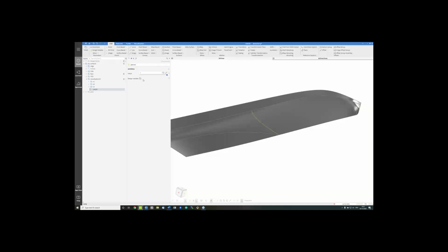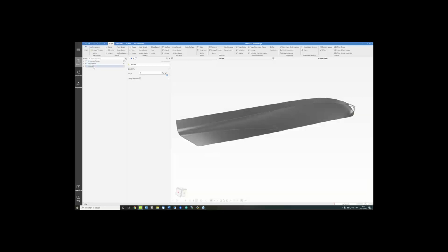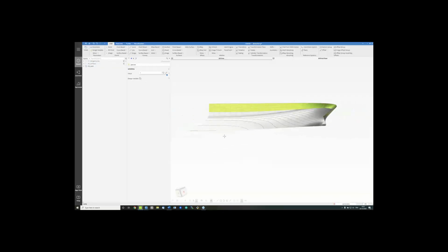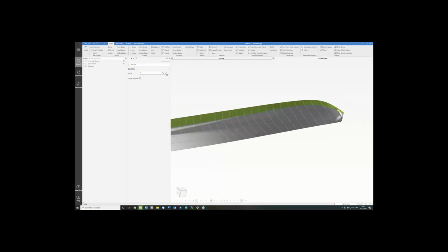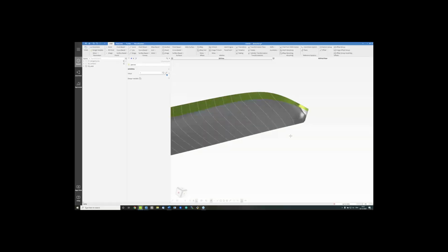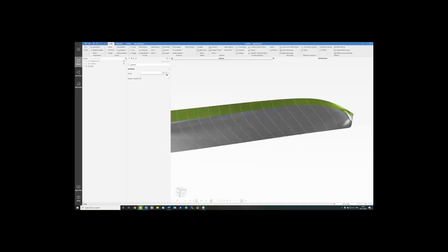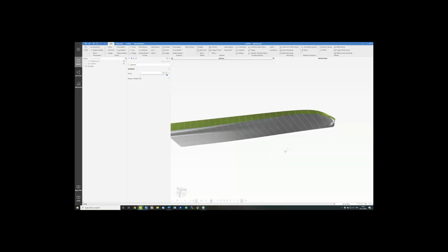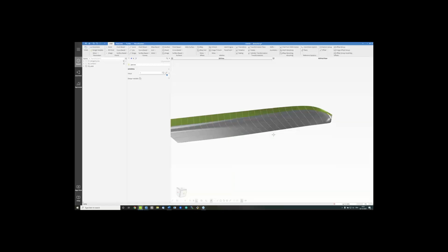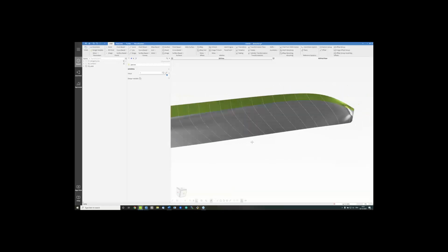And the last step that usually remains is to create a solid model from that, which could then be used in a next step. For example, hand it over to a grid generation tool, a CFD tool, or an FEM tool, so that we can run basically the same steps that I described already. Again, we would create a number of designs, calculate the steel weight, the wave making resistance, all those sort of things, and then maybe set up another response surface model based on that.